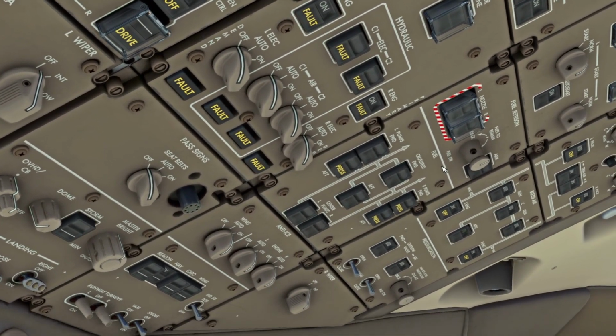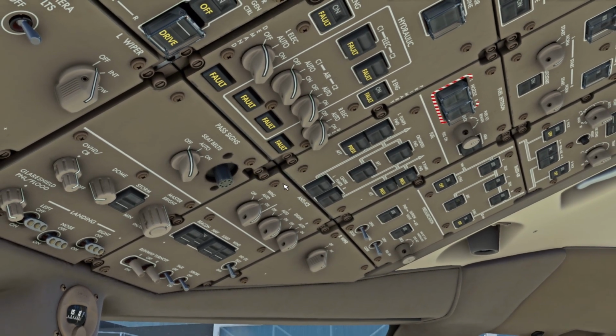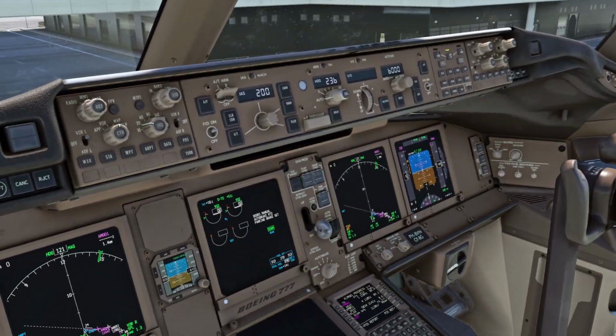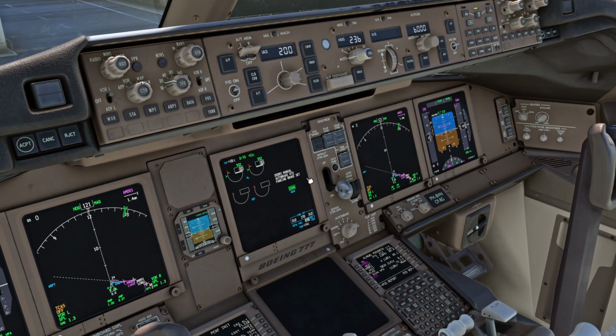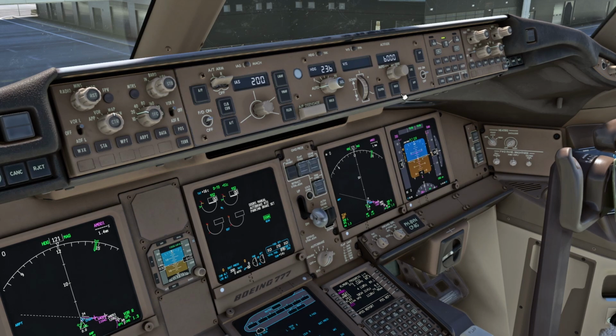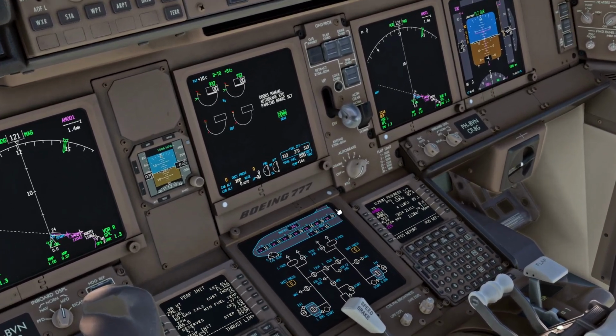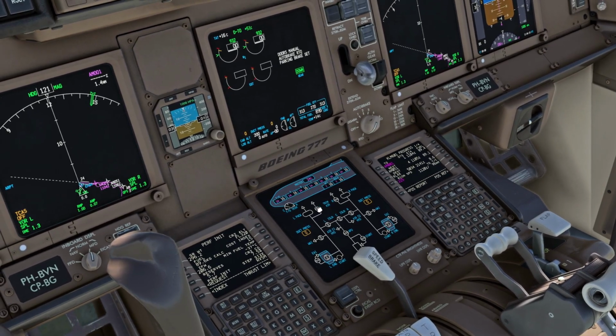Now, we've already talked a little bit about this in the pre-flight. As you can see, the pressure light of the left forward fuel pump has been extinguished right now, and that's because the APU is automatically enabling that fuel pump as it requires fuel to operate, of course. So that's kind of nice to see. Soon we'll see the APU running message here on the ICAS memo messages, and of course you can also take a look at, for example, the air synoptic to see what happens as the APU starts up. So let's take a look once we have some bleed air from that system.